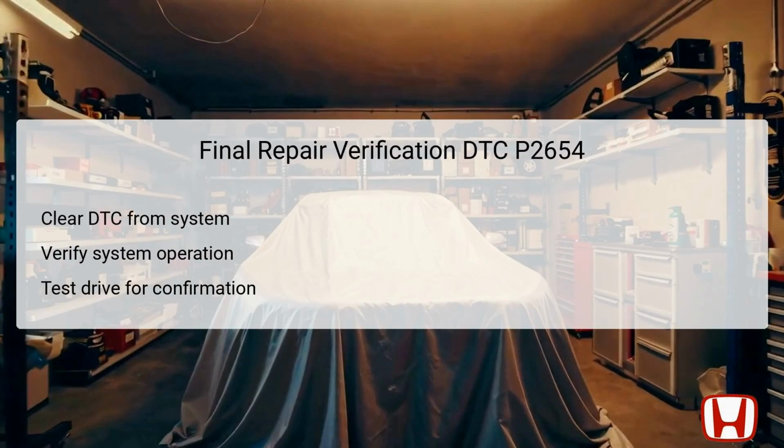Upon completing the necessary repairs and replacing any faulty components identified during the troubleshooting process, it's vital to conduct a final verification for DTC P2654. Technicians should begin by clearing the diagnostic trouble code from the engine control unit. After this, it is essential to verify the overall system operation to ensure that all components related to the rocker arm oil control solenoid are functioning correctly and that the engine is responding appropriately. A thorough test drive should follow this confirmation.